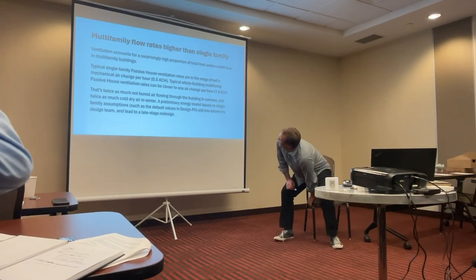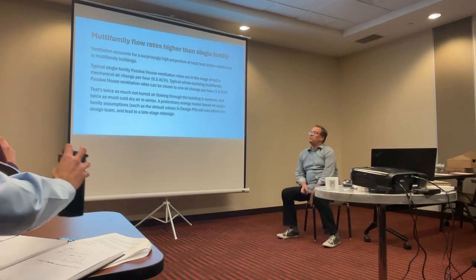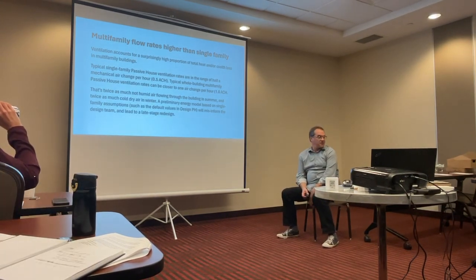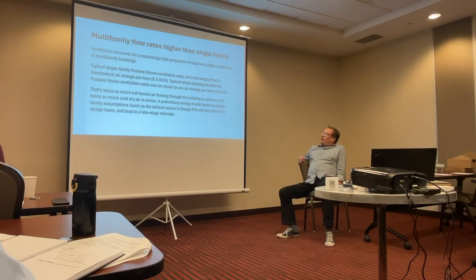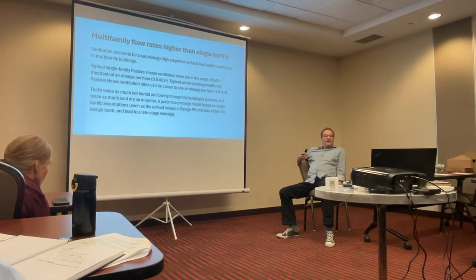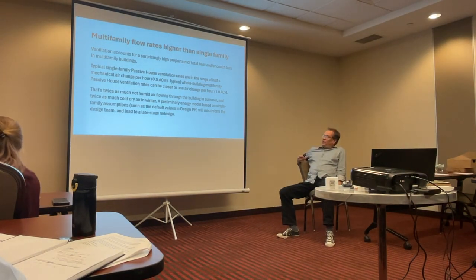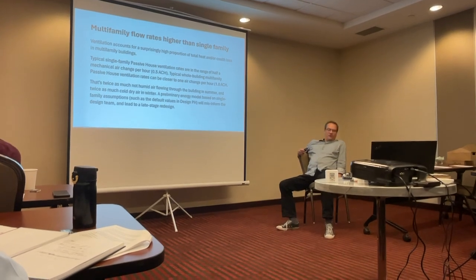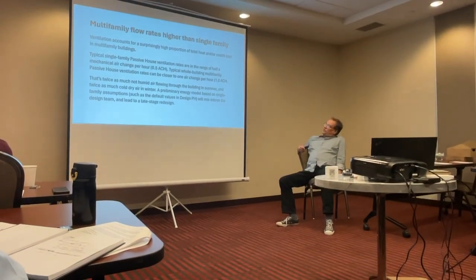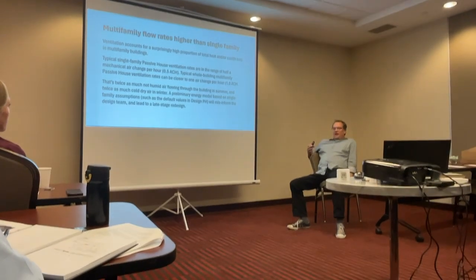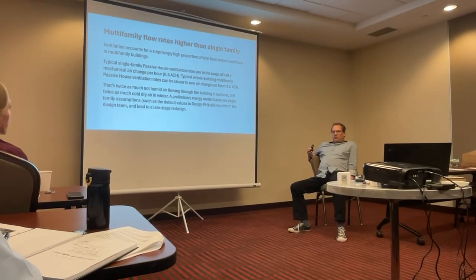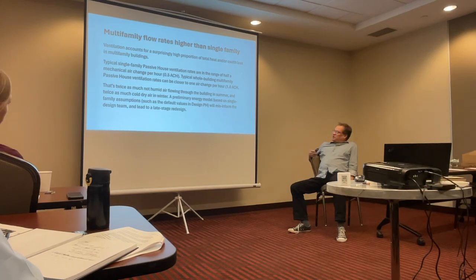Okay, this I do want to make in the show, and I welcome ideas about how to talk about it more clearly. A couple of you have hinted at it already. Our multifamily flow rates have gotten really high, and I just want to, in this book, talk about why, give an example, and talk about some solutions. And I welcome other solutions, looking at Lois and Andrew. So, we talk about how Passivhaus for years has kind of said keep your single family around 5 ACH. It gives you not so much drying in the winter, in that range-ish.